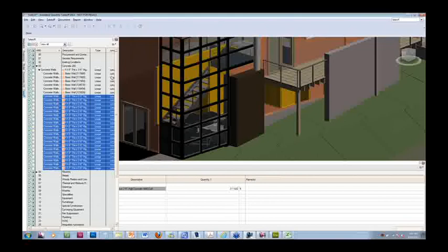So when you get a new model, what will happen is it will remember the mapping, and there's even a feature called compare, where you can compare things that exist, and it will know what's added and what is not. So it will not only show you a numerical value of what the differences are between the older documents and the newer, but it also shows you color-coded what's deleted and what's added in plan view. It's a nice feature that the DWF engine has, the ability of comparing graphically what the differences are between one revision plan and the next submittal.